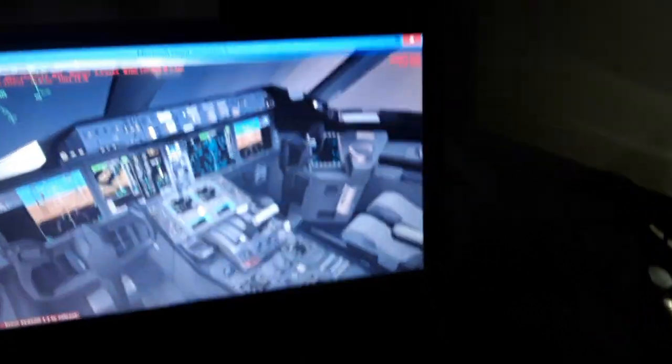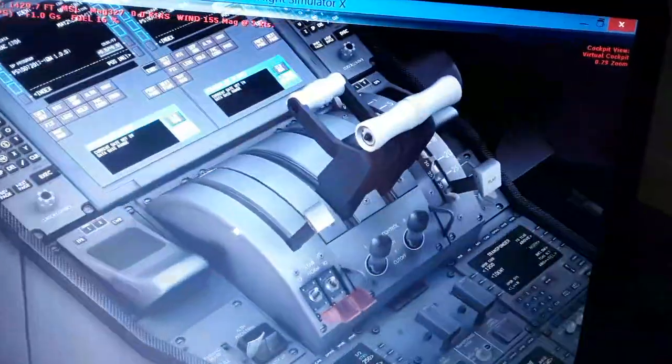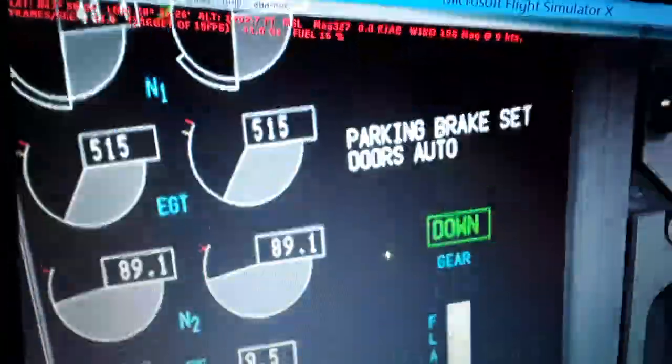we have the thrust levers here. You can see we can adjust the thrust using this stick here. So you can move the thrust levers back and forth. We can actuate the thrust commanded to the engines, by the FADEC. So we will increase or decrease the thrust commanded here.